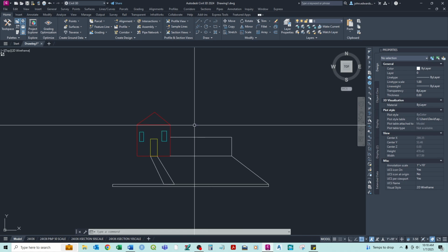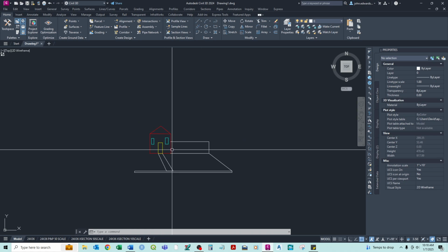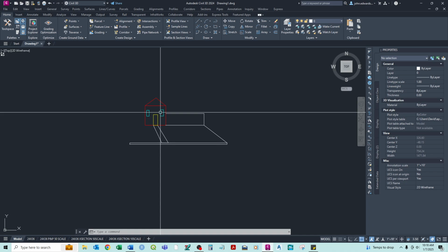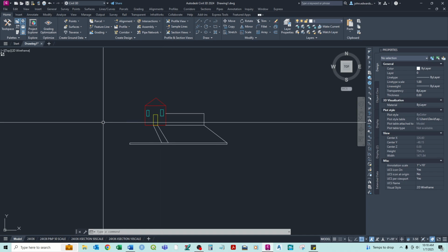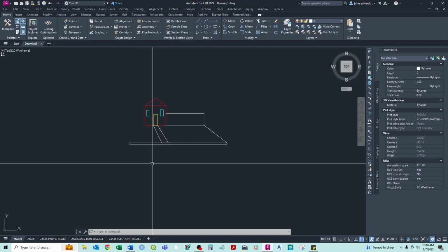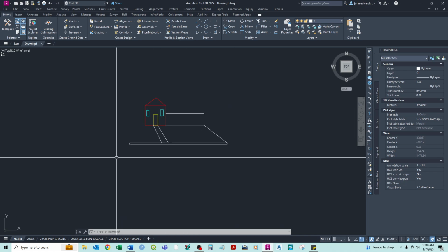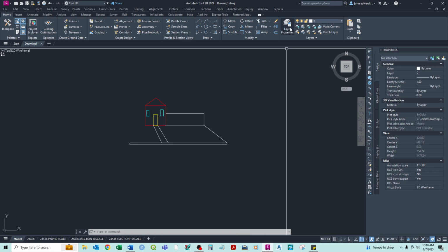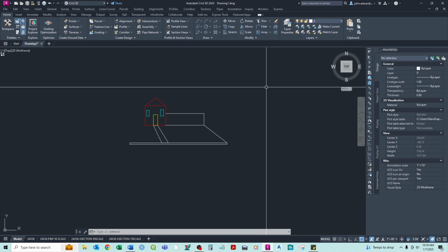Sometimes it's really useful to be able to turn layers on and off. Now this is a pretty rough example, but for things where you have a roadway on your plan sheets, you have a lot of construction lines, and that's one of the reasons I like to use a construction line layer, because when you're drawing stuff, you generally have a lot of guidelines, lines you trace around, different things like that, that you don't want to always go back in and delete, because that becomes a pain, especially in a big drawing.